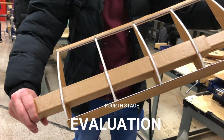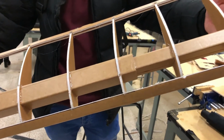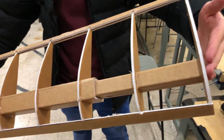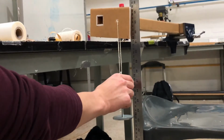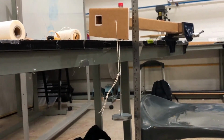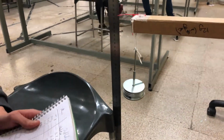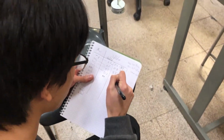For the fourth stage, the evaluation stage, the end product is tested in several ways to evaluate its performance. We had to test how much our wing could withstand in terms of both torsion and bending moment. For the torsion test, for a given force arm and weight, the twist angle can be easily calculated using trigonometry. For the bending moment test, we kept on increasing the point load and recording the deflection of the spar until the wing failed under the load.